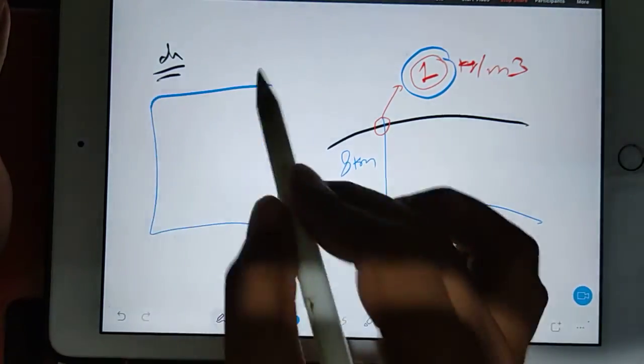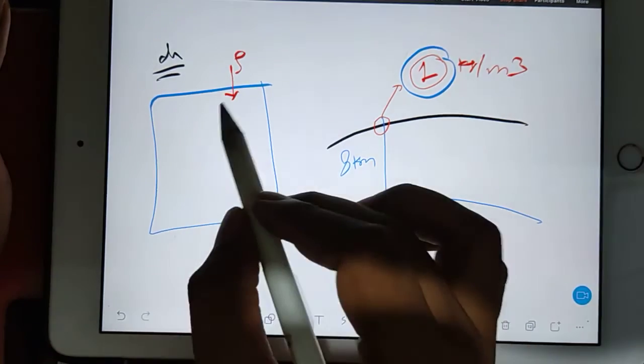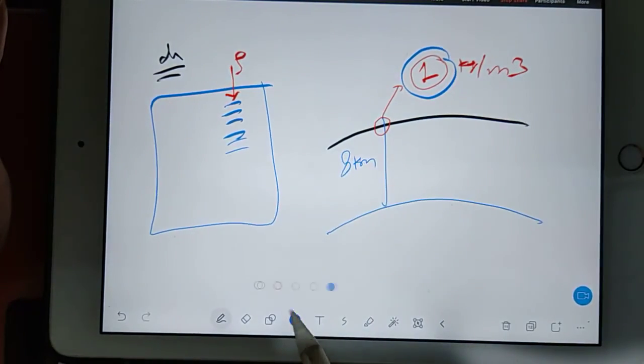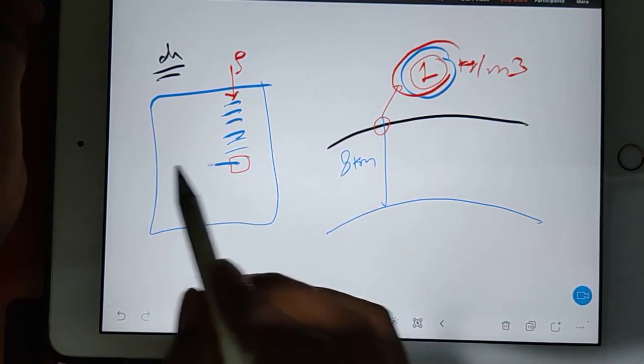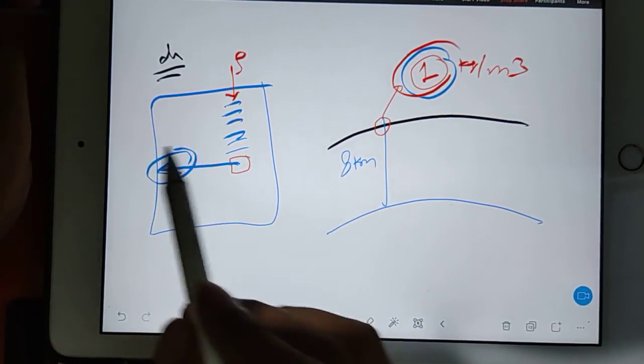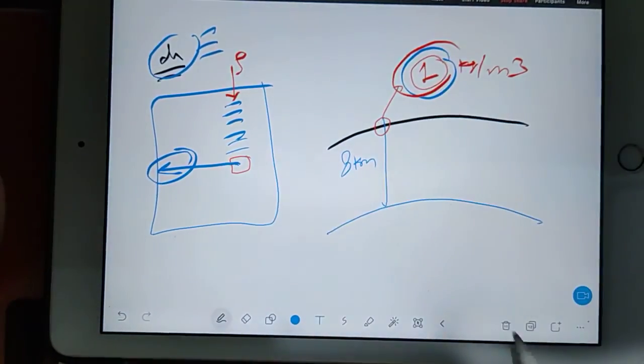Go to the ISA table. Then in the ISA table, you go to the density column. In the density column, all the densities will be listed. You check where 1 is. Suppose here is 1. In front of 1, a height will be mentioned. That height will be your density altitude. Okay, so that's all over.